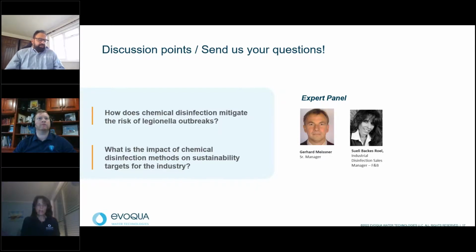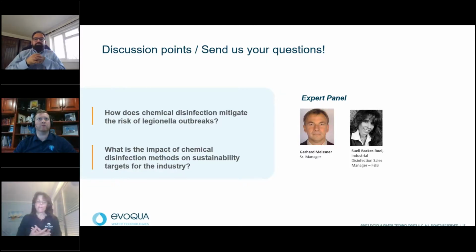Exactly. And you have to consider that if your operation is running smoothly, if you have your chemical approach with this residual, you are contributing to avoid the contamination. For example, in the cooling tower that you mentioned, you can avoid zebra mussels, biofilm, algae. All these can block the system or can generate a film.